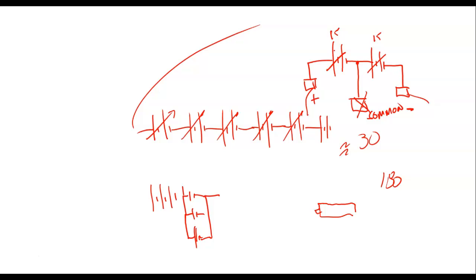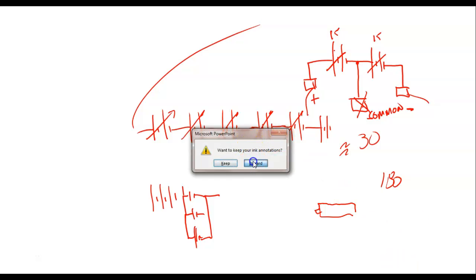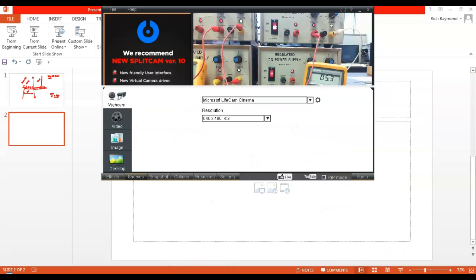You need 24 volts, so you've got a 24 volt golf cart. 24 volt batteries are very, very expensive. What can you do? You can get two 12 volt batteries and connect them in series. If you need more current, you go down to the battery man down on 15th Street in Bessemer. I've never bought a battery from them, but I've taken batteries down there.